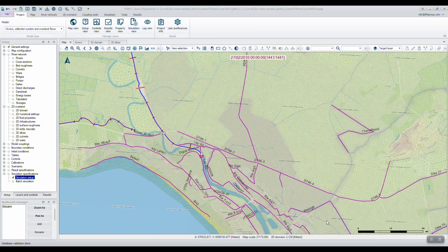In this example, some areas are modeled in a 2D model only, whereas others are combined to a 1D model describing the rivers with the blue lines here. This example contains dike structures with the pink lines, which control the flow between mesh elements, but presently these crest levels will not be shown in the cross-section plot. At first, I will show how to look at input ground levels only.